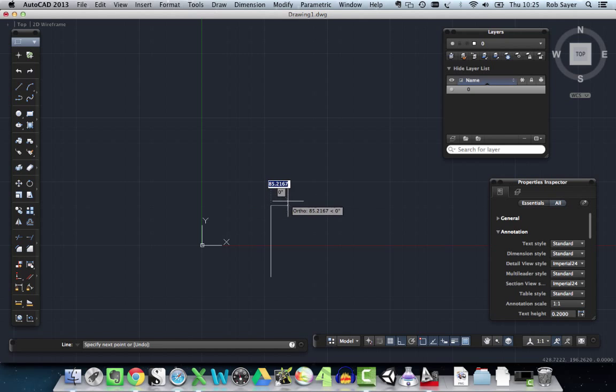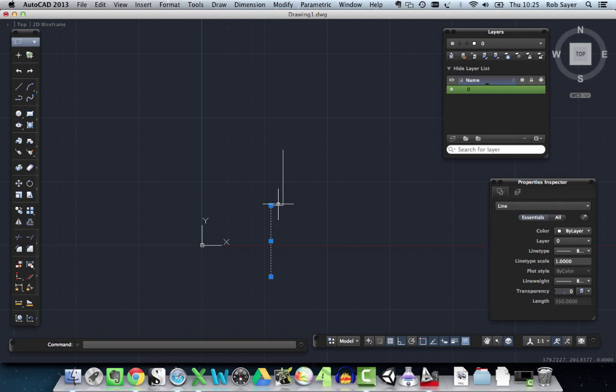Now the next part I want to draw is just a piece of wall that goes across slightly, and it's going to go across 60mm because it's not very big. So my next line is 60mm. Now going back up again, I need to carry on drawing, and this time it's 270mm. Now if I just hit escape and stop drawing, you can see I've drawn this kind of wall shape here. This is like a brick pier or something. And basically it's 3 individual lines.